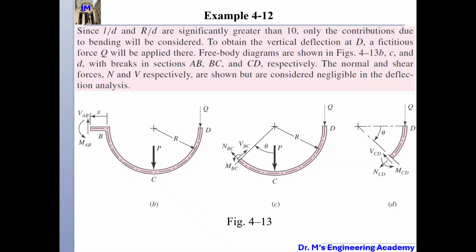So this is a transverse shear force along with the bending moment, and these two are going to balance the force and moment generated from the right hand side. For the right hand side, we have a P here, so this is the actual force. And also we have a Q here, so this is a fictitious force. You guys agree? So for this generic point x, this is my origin, this is my x, right?